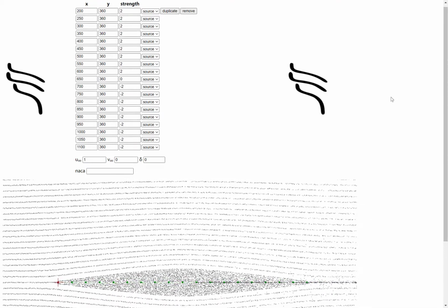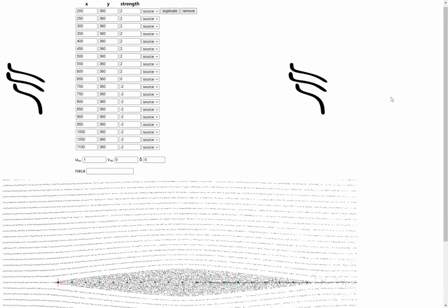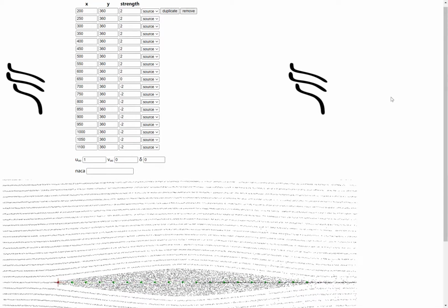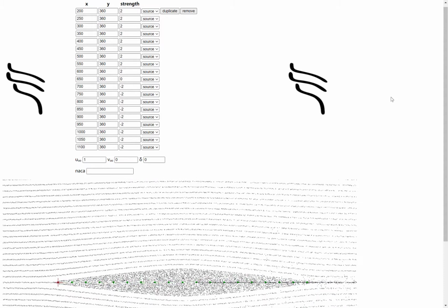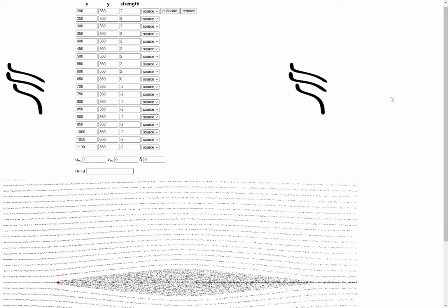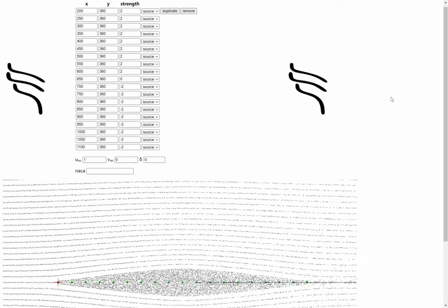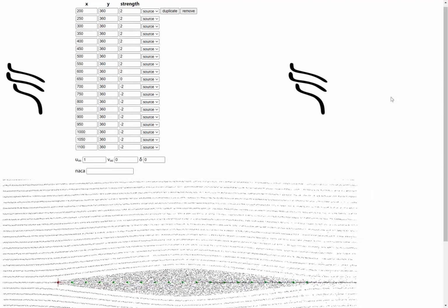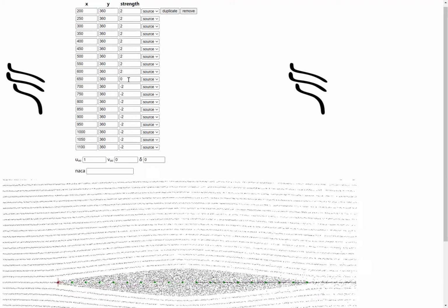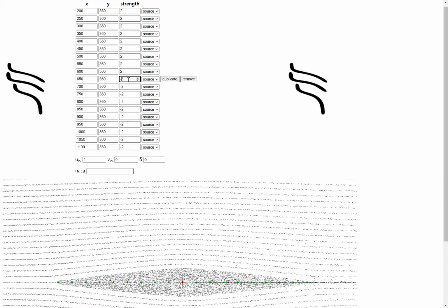For example, let me challenge you to change the shape of the airfoil from a diamond shape to a hexagon. I want to trim the top and bottom of the airfoil from maybe 1/3 to 2/3 into flat surfaces. How would you change the sources and sinks to do that? Yes? I'd put stronger sinks in the middle, about 3. Put stronger sinks in the middle, right in the middle. Yeah. So if I make it 3 or -3? -3.